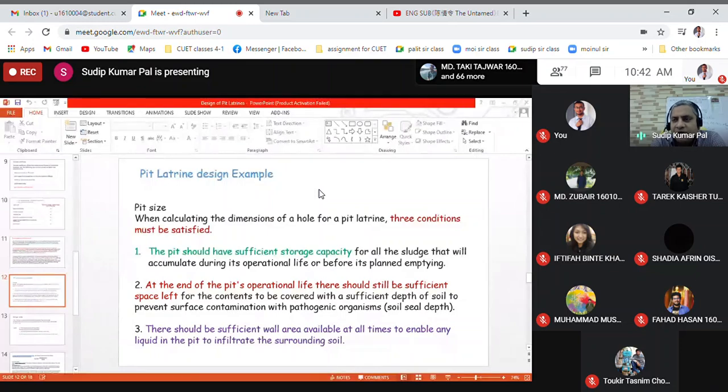Right now, it's better if you can keep some data in your head. I mean, preferably, because it's not about memorization, it's about understanding. For example, coarse sand or medium sand have more infiltration capacity because their pore size is much higher compared to clay. So if you understand this sort of data by reading the table, that will be fine. That is my point.